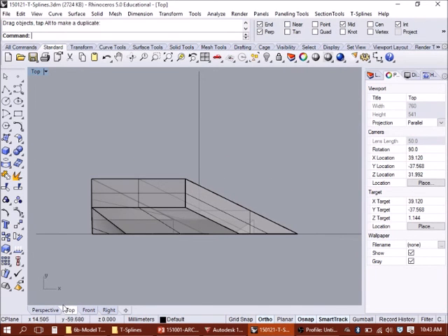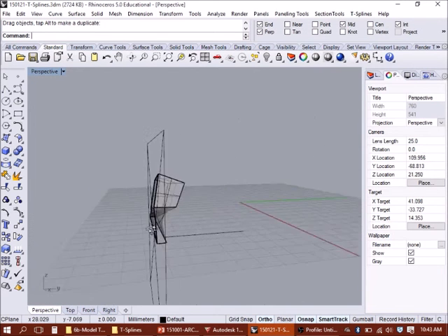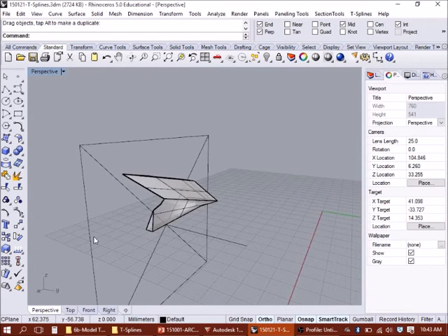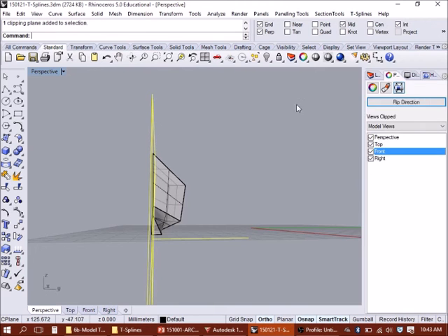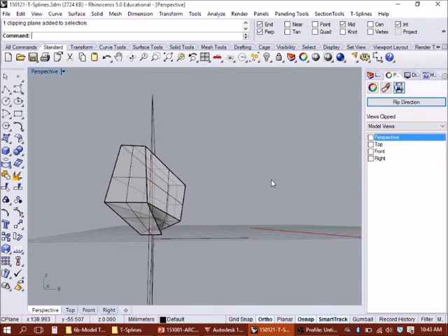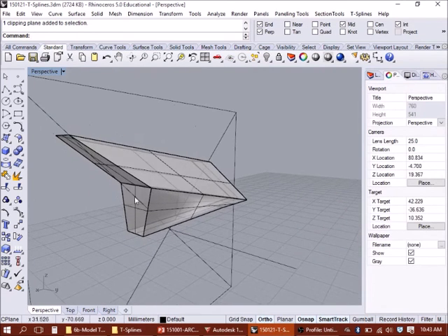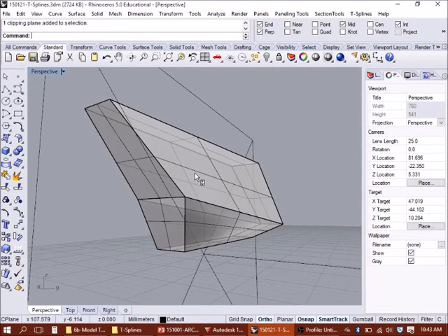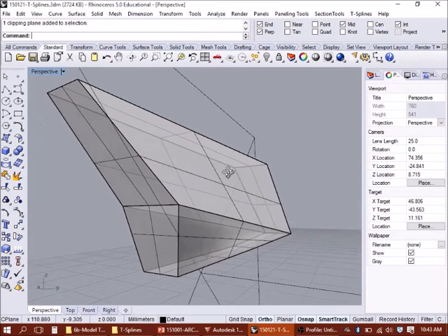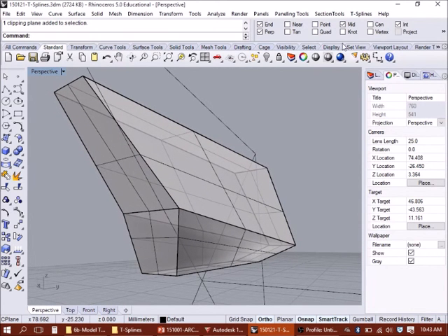No. The other thing that you might consider to work with in thinking about translating or transferring drawings from Rhino to hand drawing, and this might be good for the perspective drawing. So I'm going to turn off this clipping plane, just in the perspective view. Is that I can do something that's called Make 2D. Command called Make 2D. So say this is the view, I'm happy with this perspective view, and I can go into